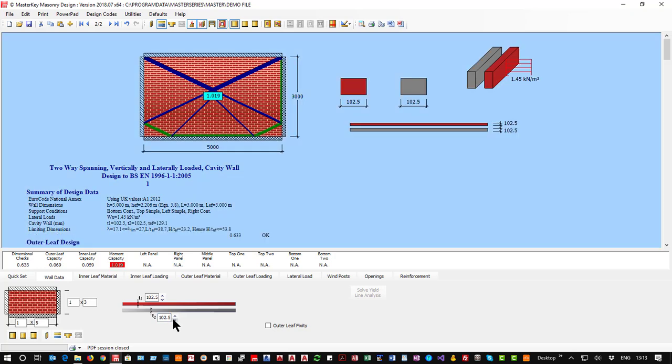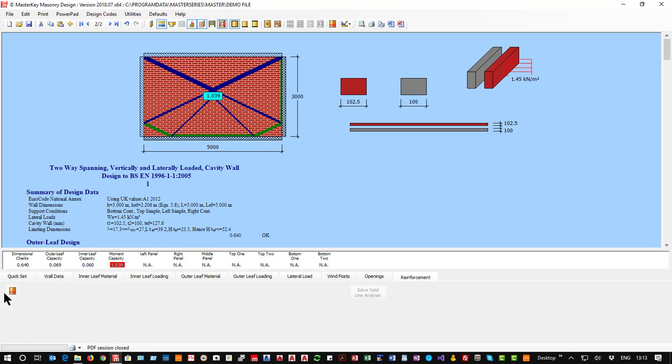If I wanted to come back and stay there, didn't want to reinforce or make this other side continuous, my next option is to put on some bed reinforcement. So we're stepping through the ways of making our wall stronger.